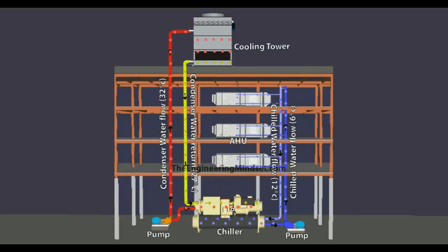Now, chillers come in all shapes and sizes and thermal ratings, and that really depends on how much unwanted heat the building is producing. This unwanted heat comes from sunlight, people, and the equipment within the building. Even the chiller itself will generate quite a fair bit of heat as it produces this chilled water. So the system will all be designed to cope with this, to reject that heat and produce enough cooling as it was designed to do.